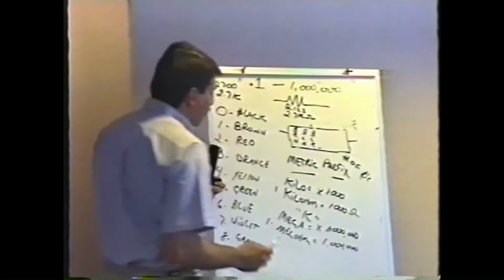So, same thing, and if you look again at your meter, for those of you that have this type of meter, or something similar, you'll see that the two highest scales are megohms. There's a 2 megohm scale, right? And the next one up would be 20 megohms.